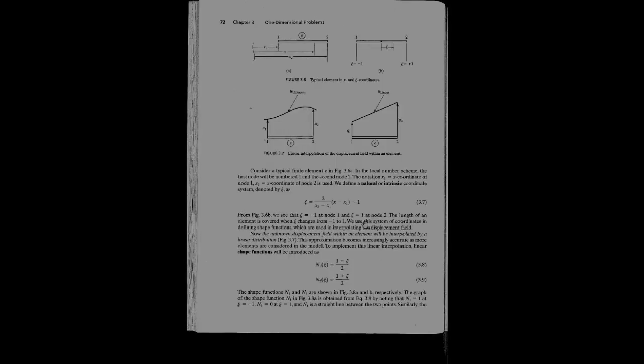And this is really just to get you comfortable with taking a linear superposition of these things and essentially building up a displacement field. Each one will be multiplied with Q1, Q2, Q3, Q4 in the end. When you superpose them all, we get a displacement field out. If you do linear elements, you have a linear field. If you have quadratic elements, you have a quadratic field.